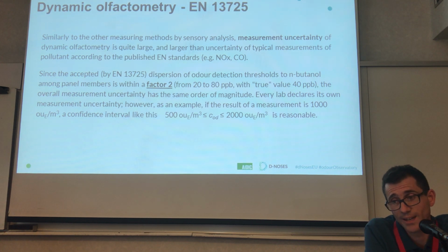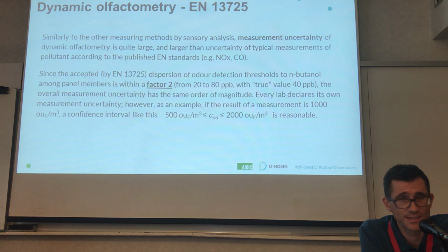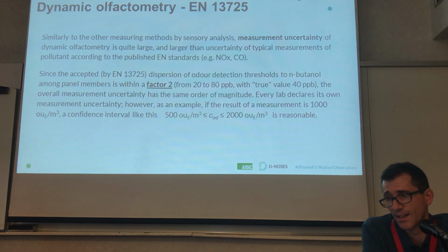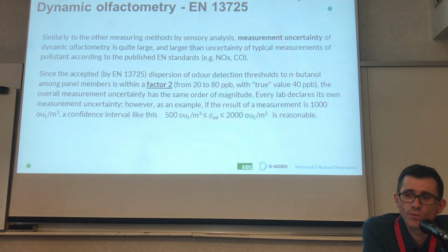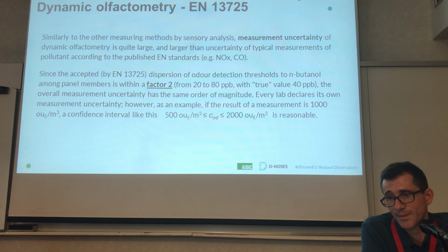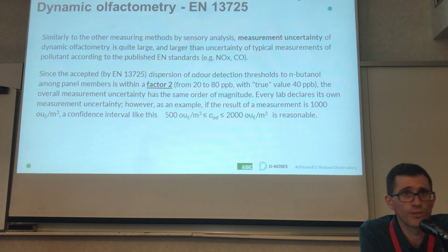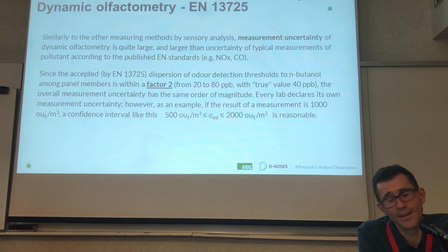Similar to other measuring methods by sensory analysis, the measurement uncertainty of dynamic olfactometry is actually quite large, and larger than the uncertainty of the other typical measurements of air pollutants.